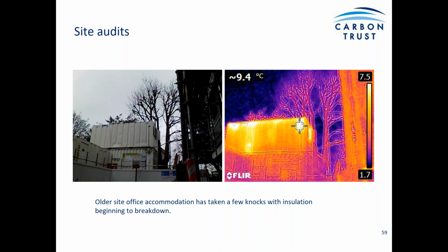You can see where we've turned the thermal camera on it, where the impact of the damage on the outside has impacted the insulation, and has rendered quite a bit of it useless. I'd suggest probably that it's a result of the insulation getting wet.